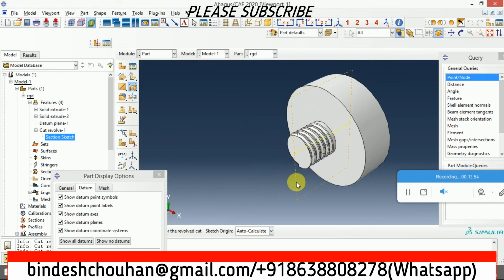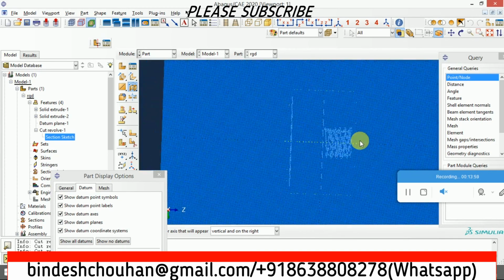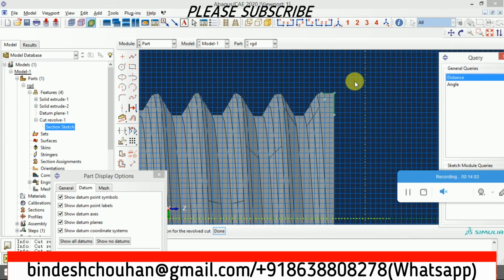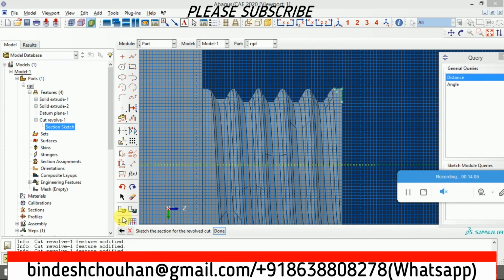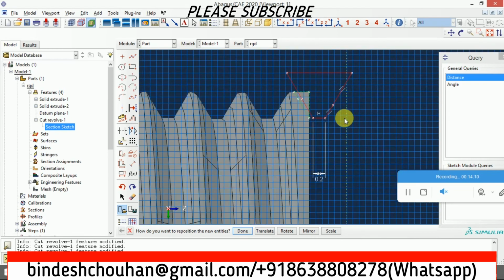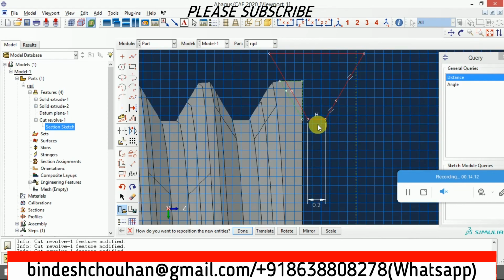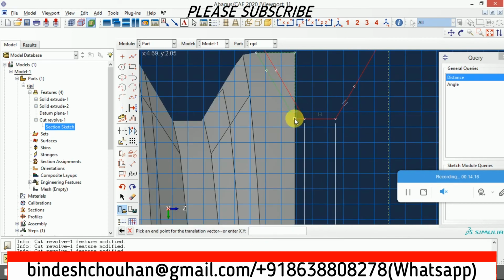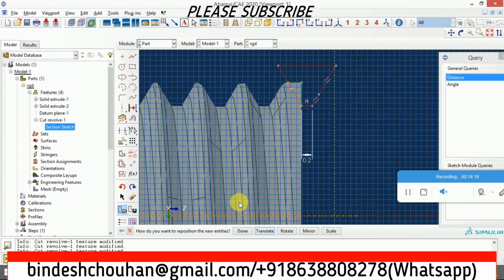I'll again make a revolve cut, go again the same way, and I'll bring the sketch 1 over here again. It has not been placed properly, so I need to translate it. I'll translate this one to here. So now it has been placed properly.